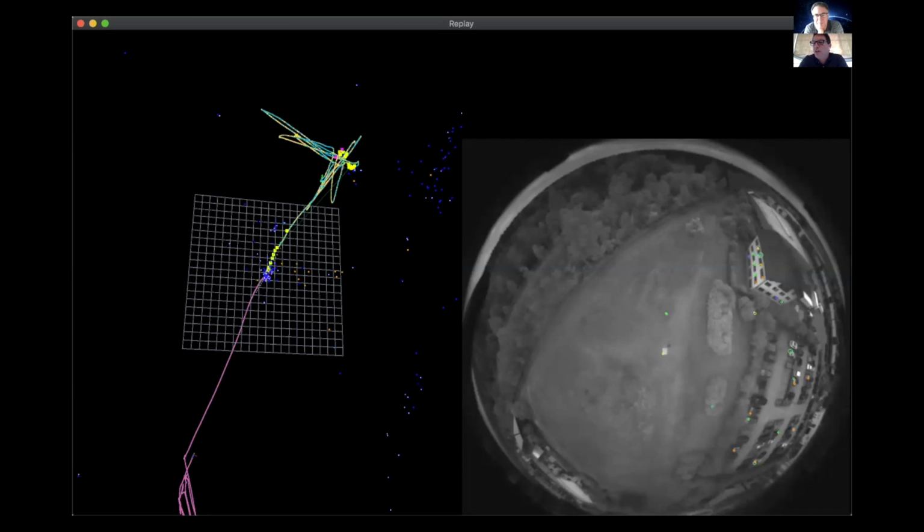The algorithm's generally asynchronous. We get in IMU, they can run at different rates, but they're at least all on the same clock. So one of the problems when you build this stuff yourself is getting time synchronization. Getting good, accurate IMU data, and accurate time synchronization. If you were to use this system, at least that part would be solved. You don't have to use our algorithms. Instead of just taking our pose, you can take the raw data and run your own algorithms on it. But at least in that case, you get nice time synchronization.